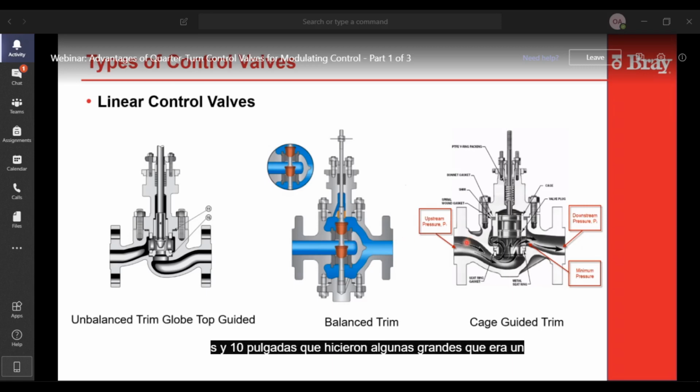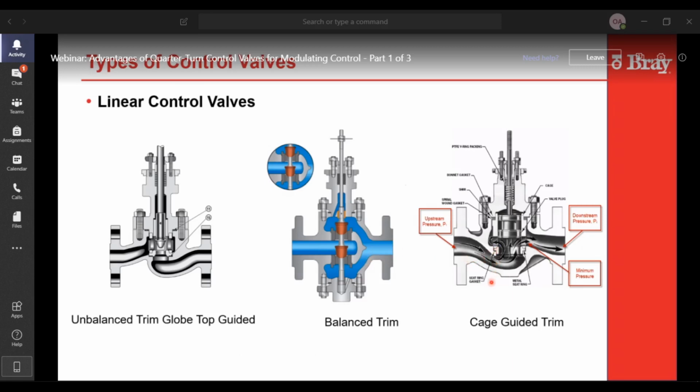It was an excellent control valve. The flow characteristics were excellent, but because it could not load both seats equally, especially if you had thermal transients, it leaked a lot. So usually it was rated a class 2 shutoff. People wanted the control valve to do everything. So they wanted it to be a shutoff valve as well.